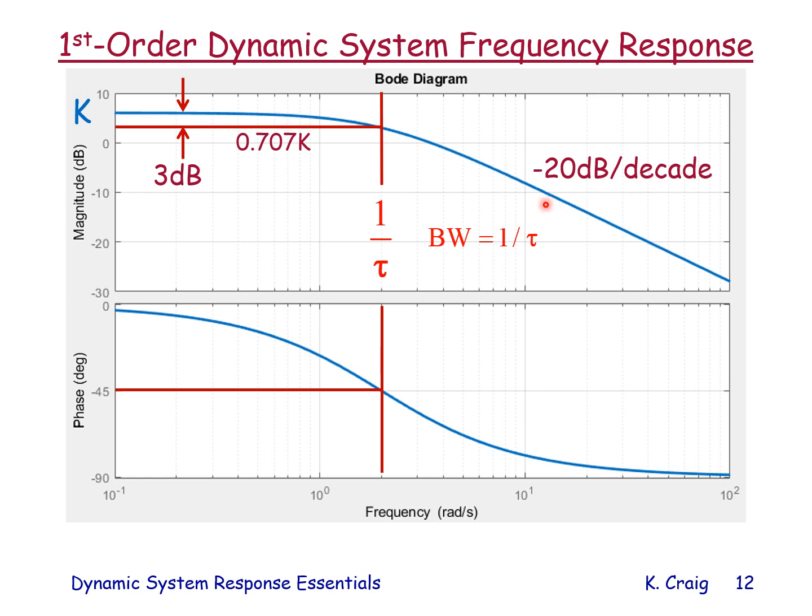And you can see that right here. From here to here, it drops 20 dB over this decade, from 10 to 100 radians per second. So this is the Bode plot, or the frequency response plots, for a first order dynamic system in terms of the parameters tau and K.